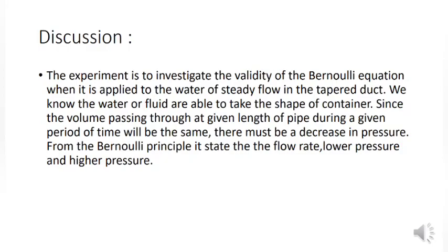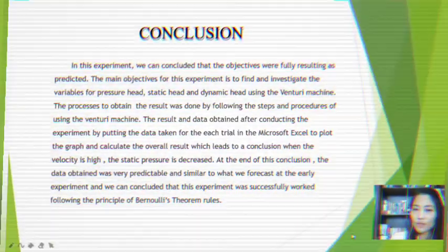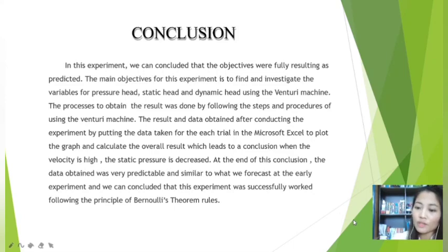Thank you. Assalamualaikum. So hello, I'm here today to present the conclusions of this experiment. The static pressure is reduced as the velocity increases, and in this experiment we can conclude that the objectives were fully met as predicted. The main objective of this experiment is to find and investigate the variables for pressure head, static head, and dynamic head using the Venturi machine.